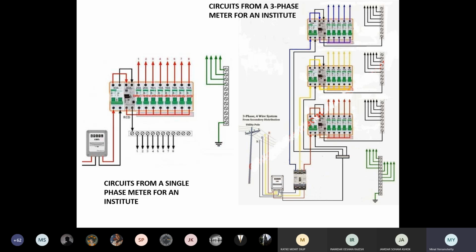And that means he will have a computer, he will have a charger, he will use this many fans, he will have an AC, and all that comes within 1 hour, within 1 day. And that was the reason why I gave you that formula for how you calculate kilowatt per hour. If I'm using my computer for 8 hours, I will have the wattages ready because it is available in the units, and then I multiply by the number of hours. And so I know the total units I am using per person per day in a house. I can calculate the total load approximately.